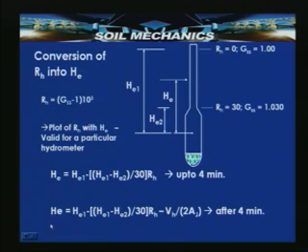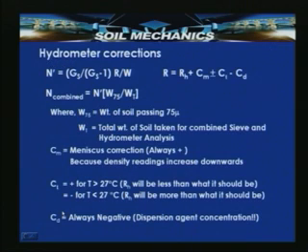Once we measure RH and correct for the immersion correction, we are converting that into effective height. From there, by substituting in the Stokes law, we will be able to estimate the particle size at a particular time. So now coming to this, whatever we have seen previously, the percentage finer N dash is equal to Gs by Gs minus 1 into R by W.